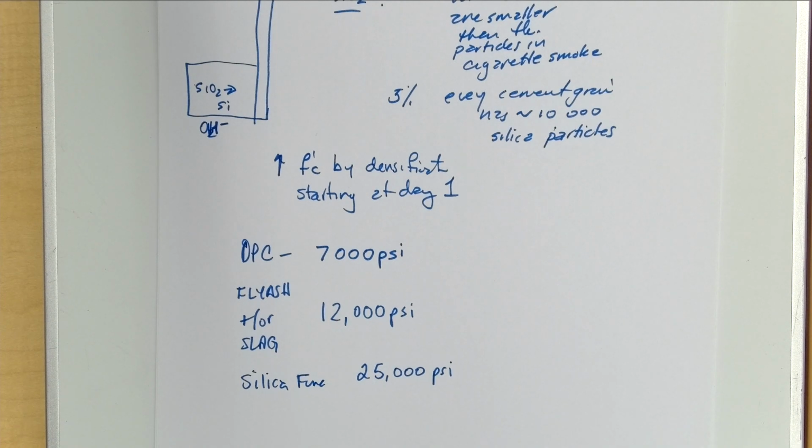And the St. Croix Bridge recently completed. By the way, the project manager on the St. Croix Bridge, where did he go to school? UW Stout. They had transfer beams at the top of each of the piers that consisted of a quaternary blend: cement, fly ash, slag, and silica fume. Carefully proportioned to give us concrete that the state said they didn't think could be made. So that'll teach them. And that's what I was hoping to do.